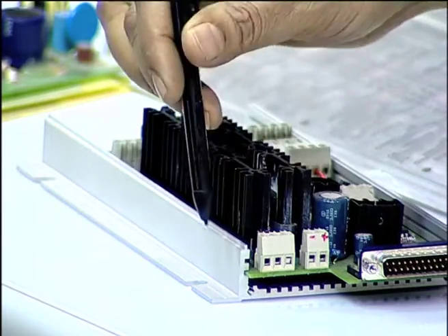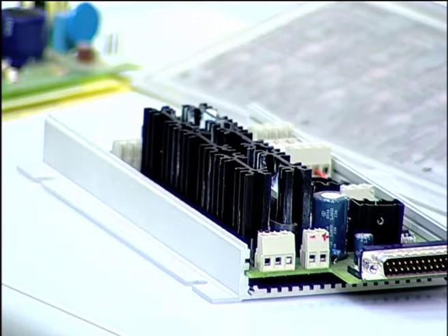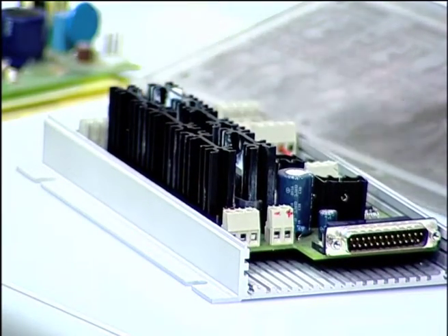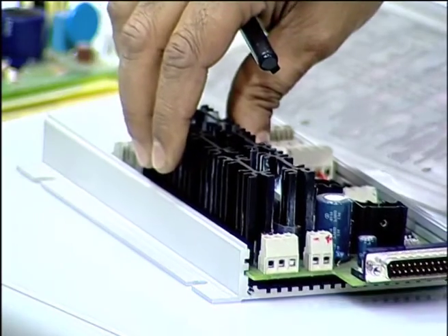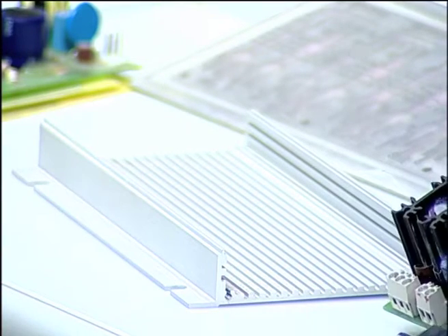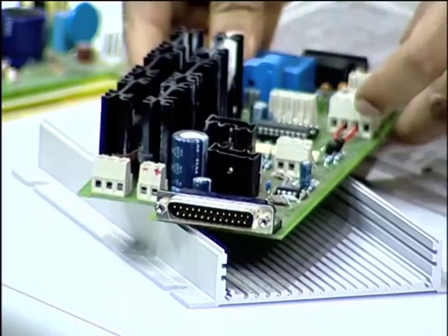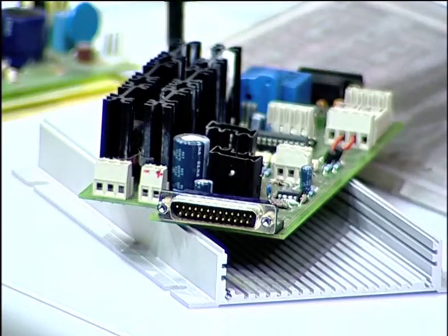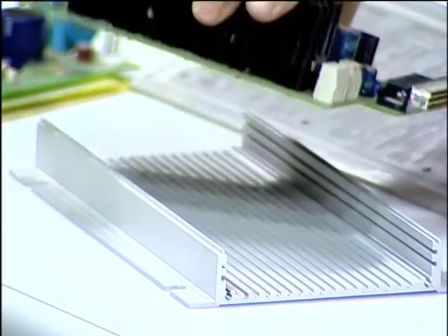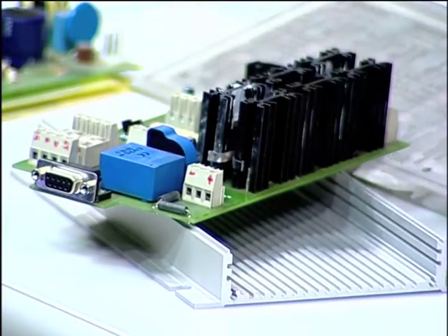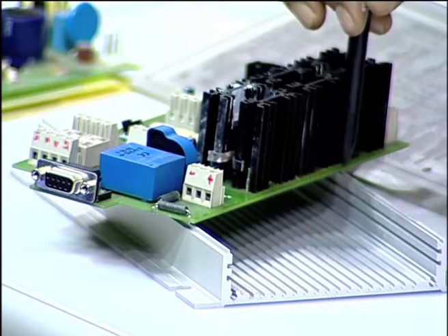Now, these card guides may be metal or non-metallic, but one important thing about these card guides is that you should not have any components for that space of 2 mm or so, all this space here and so also on this side where you are going to have the card guide.